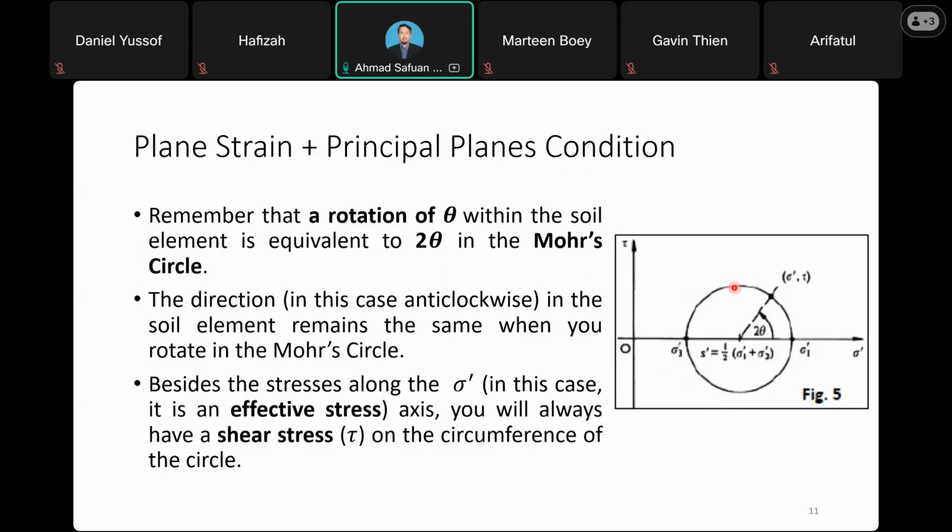Okay, so that is for the Mohr-Coulomb plane strain concept. Now we may relate it with the drained and undrained conditions. We use sigma prime for effective stress analysis if the geotechnical event involves coarse-grained soil, or for long-term stability analysis in fine-grained soil, called effective stress analysis.